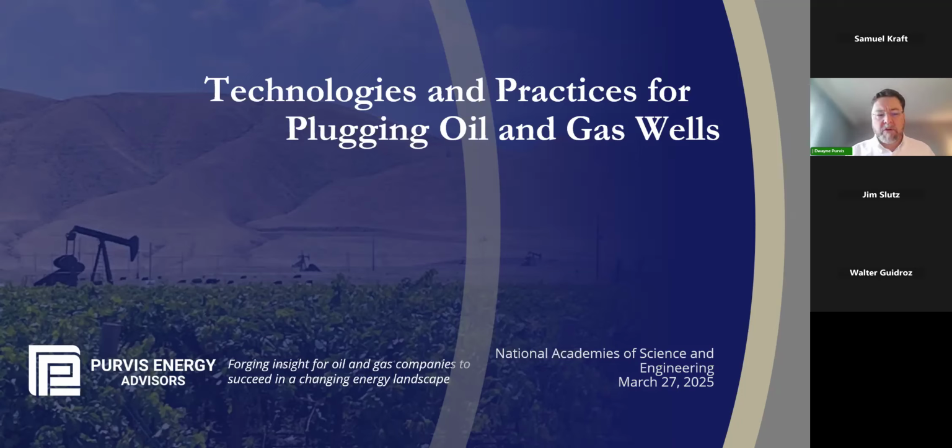And I was watching a video from a company earlier this week, and they argued that at the end of the well life, we were going to fill the well with cement. But that's not true. What we do is put cement in critical points in the wellbore, but we leave 80 to 90% of the wellbore open, where there's nothing but liquid. So we've taken what was 100% rock and reduced it to 10 or 20% rock, which leaves it much more open, with many fewer barriers, less restrictions.